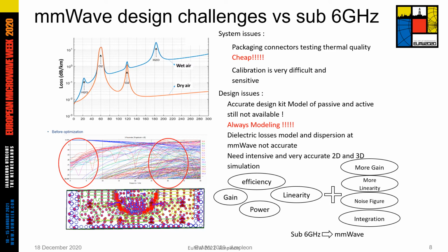Here I'm going to give an example. This is a design of a multi-channel transceiver, with a transition to the antenna. It is designed to be 50 ohm based on theory, and as you see here, even the theory based design works fine at sub-6 gigahertz.